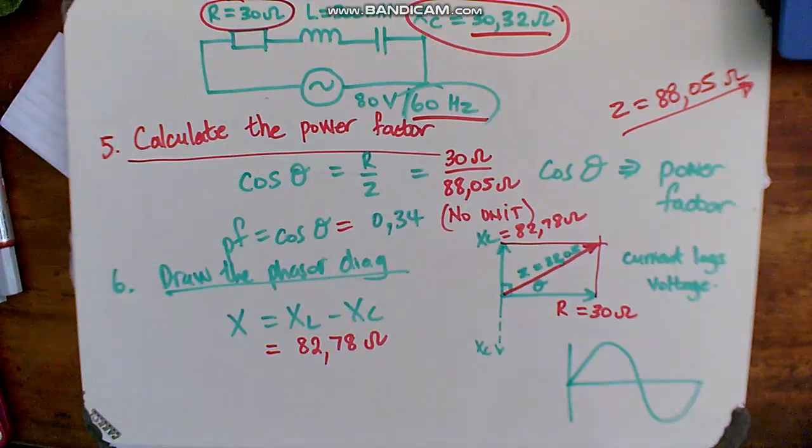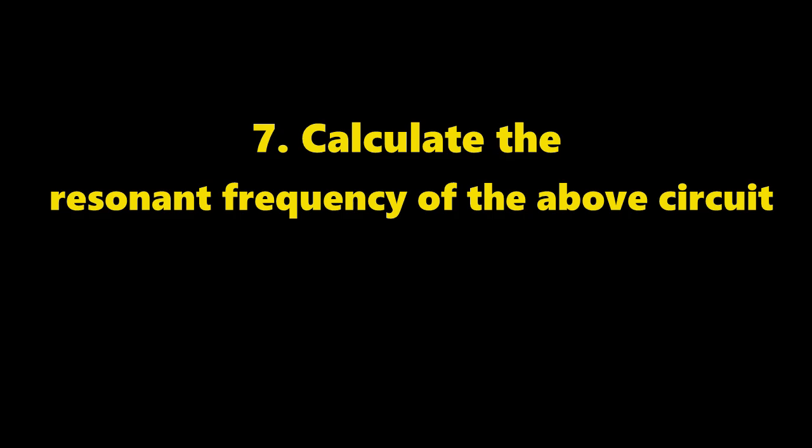So you could work out the angle theta by saying cos minus 1, 0.34. You should get around about, I'm not too sure, maybe 0.8 or something like that. Maybe about, sorry, not 0.8. You'll get about 80 degrees or so, 70 to 80 degrees if you work that out. And that will be how much the I is lagging the V. Okay, it'll be lagging by that amount. So let's say if it was at resonance, this means V and I would start at exactly the same point.